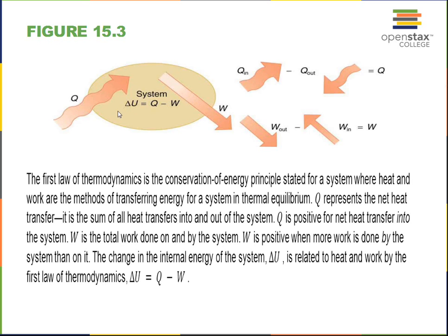If Q comes out of the system, then Q will be a negative number. And also, if the system is worked on, for a gas, if we're compressing the gas, we're doing work on the gas, then W will be a negative number. So you must learn to recognize when Q is positive, when W is positive. Q is positive if energy goes into the system. Q is negative if energy is withdrawn from the system. W is positive if the system does work, and we'll mainly talk about gas systems here, so that's going to be the system expanding, and the system doing work. If we're compressing the gas, then W will be negative.